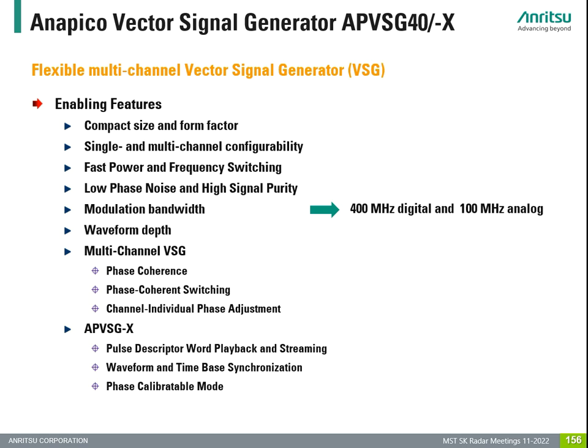In part 1 of our webinar, we have discussed pulse compression techniques. We heard about the so-called chirp bandwidths. In practice, we see typical chirp bandwidths from some hundreds of kilohertz to some tens of megahertz. These are real-world chirps. In industrial applications or automotive applications, the chirps have a much wider bandwidth.